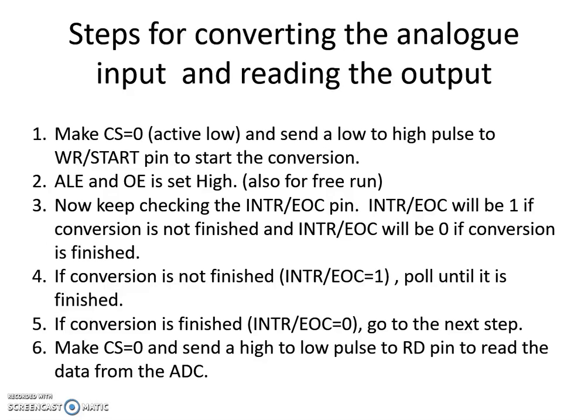OE is set to high, also for free run. That means if you want to make the ADC chip run as free run, you also need to set it to high. And then keep the interrupt, or EOC, the end of conversion pin, high.